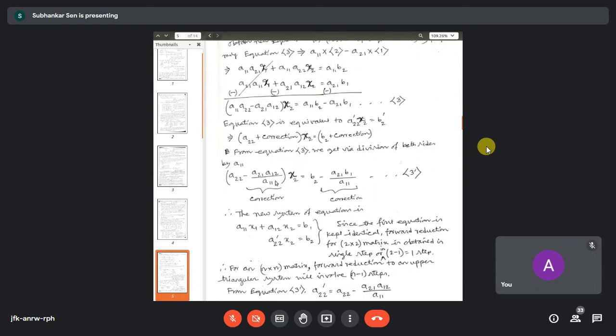So when you are dividing by the diagonal term, it must not be 0, or it must not be close to 0. Because of that, you have to do pivoting if pivoting is not done. So when you are using the central difference scheme for the convective term, and if you don't follow some guidelines, you get some wrong solutions or physically meaningless solutions.